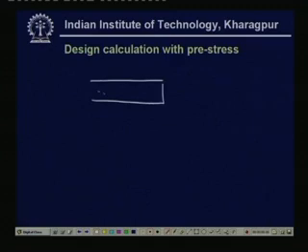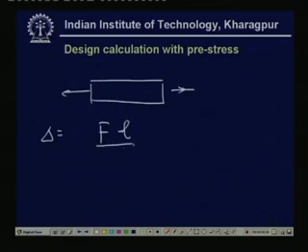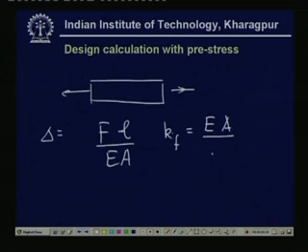If we apply force, then the deformation delta will be equal to F times L divided by EA. Therefore Kf is almost equal to EA divided by L.